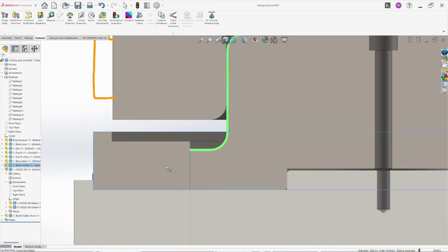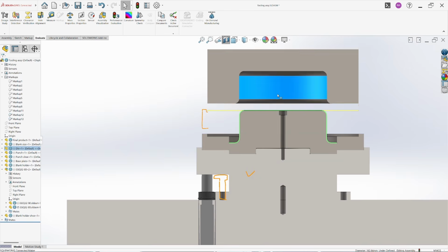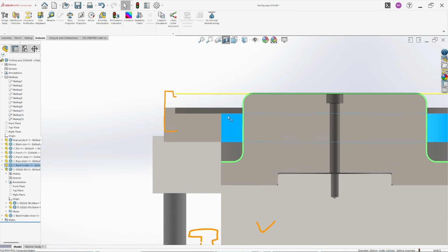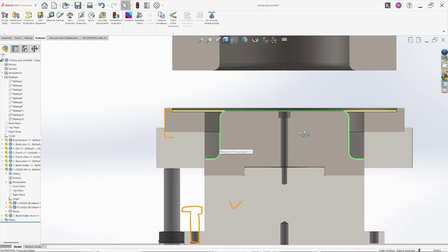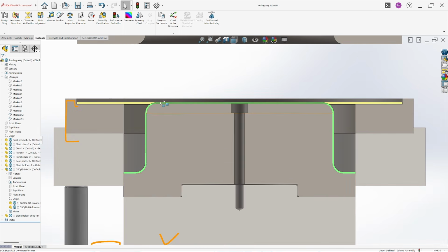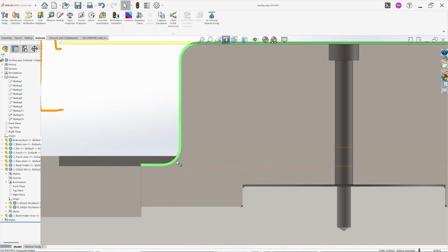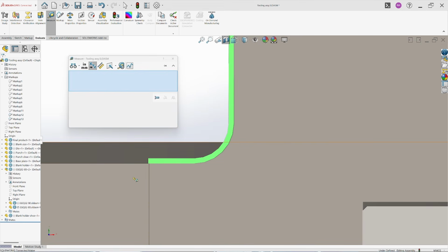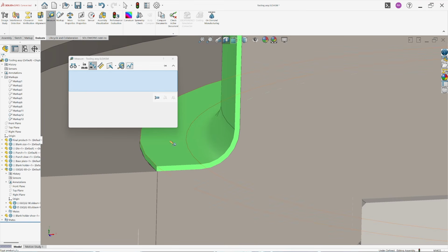It will not go up with the blank holder. So when our die completely takes off, our blank holder will reach its initial condition and our final product will remain inside the punch and this blank holder, and it will be very difficult to collect the final part, right? So we will have to make sure that some part of the final product after the drawing remains over the blank holder. And the part that we can leave over the blank holder is the sheet which is not formed.